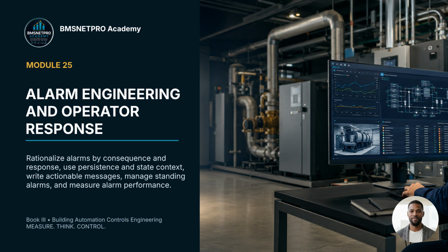Welcome to Module 25, Alarm Engineering and Operator Response. In this module, we treat alarms as engineered decisions, not as automatic notifications from every point. An alarm is justified only when a defined person can take a defined action within a useful time. We will learn how to rationalize alarms by consequence, use persistence and state context, write messages that guide action, manage standing alarms, and measure whether the alarm system actually helps operators respond.